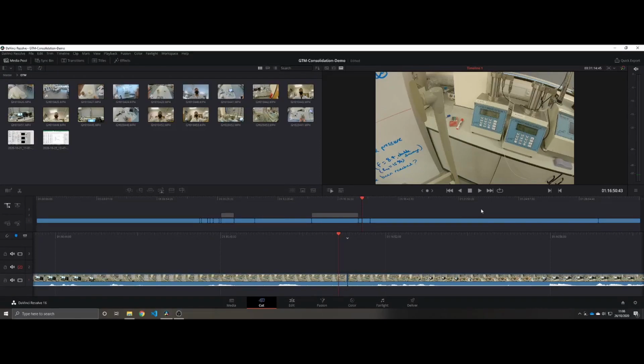Okay, as I'm editing this back, you might have realised, and I realised, that I've just become quite confused, and I just want to talk briefly about the reason for that. There's nothing wrong with what happened, but the increase in back pressure caught me slightly off guard. The software is clever enough to know that when you increase your consolidation pressure, you want the change in P dash to be almost instantaneous. You don't want it to ramp up over time as the cell pressure increases. So what happens is the cell pressure and the back pressure increase at the same rate until the cell pressure reaches its specified value, and then once that happens, the back pressure will drop almost instantaneously to give the correct new value of P dash.